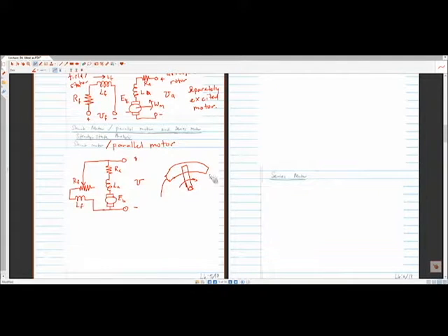If you rotate this more to the right, the length of the resistor gets longer, therefore the resistance increases. If you rotate it to the left, it decreases. This is connected to a wire as well. So this is just a way in which you're dialing or changing where you are touching this resistance strip, and that's where this symbol comes from.